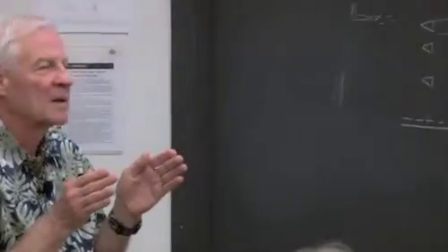In the thermometry example I just showed you for NO, I remember we took our pictures about every 100 to 200 nanoseconds. So we had to wait 100 nanoseconds before we did it again to get all the photons. But you had to take the picture fast enough that there's no motion. So if you had a low density flow where Q is smaller and a high speed flow, you have to be careful. Because you want to take your pictures fast enough there's no blurring, but if you take them too fast, you may not get enough photons. So you have to always pay attention to Q and your flow speed.